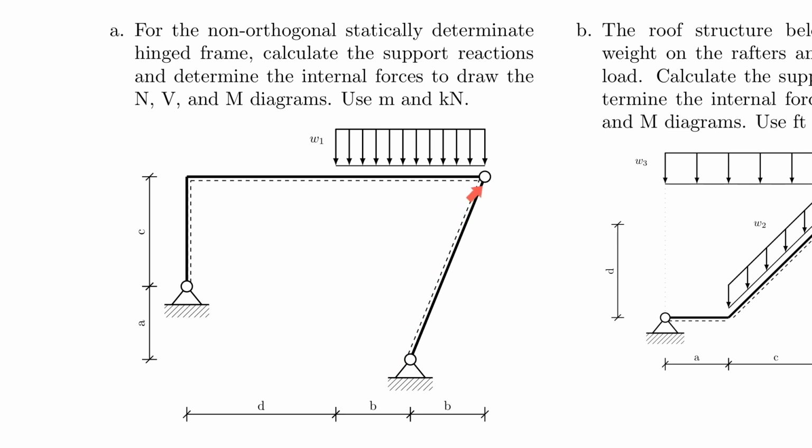In fact, in terms of what's going on, notice that this here is a non-loaded beam, if you want to call it that, or a column. It's something in between a beam and a column, but it's not loaded. That prepares you for some topics that we cover after the exam, but more on that later. For now, just know there's a hinge here, and there's no load here. That tells you something about the shear force and the bending moment diagram, and I let you play with that and practice that as an option.